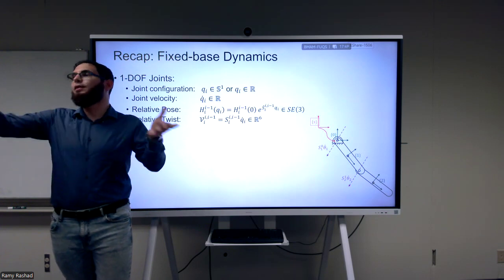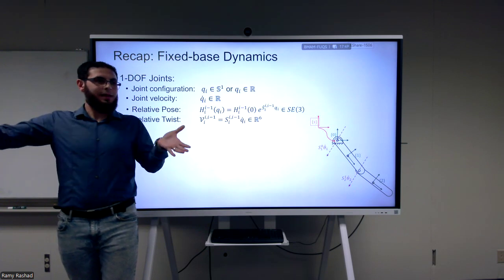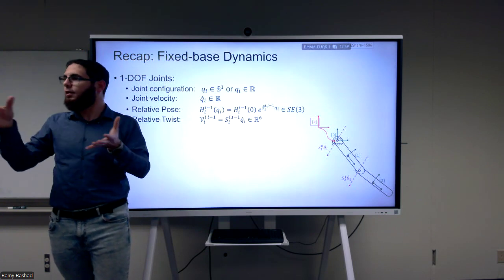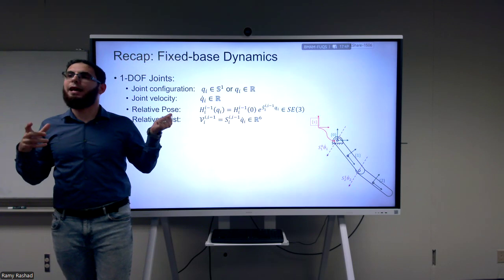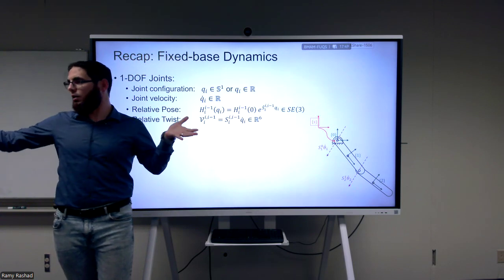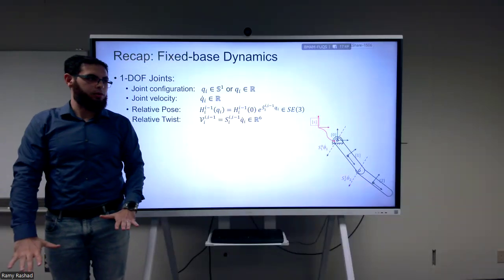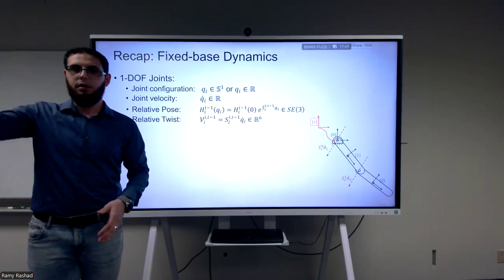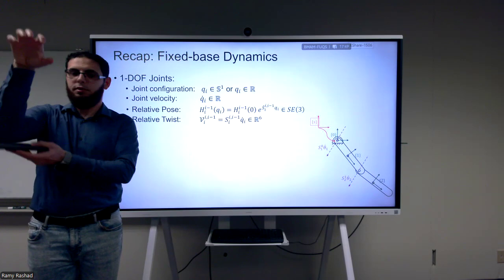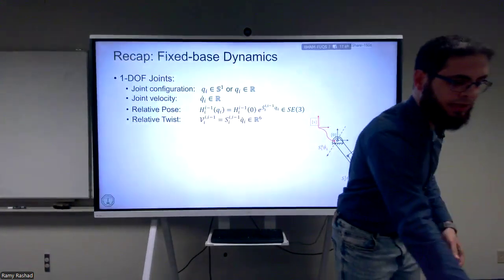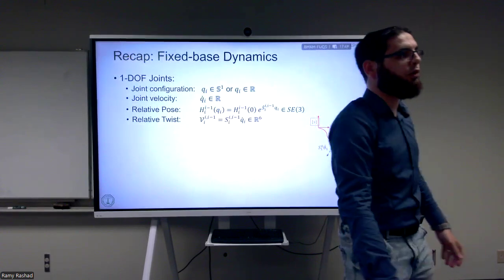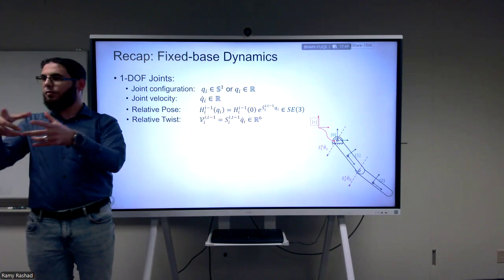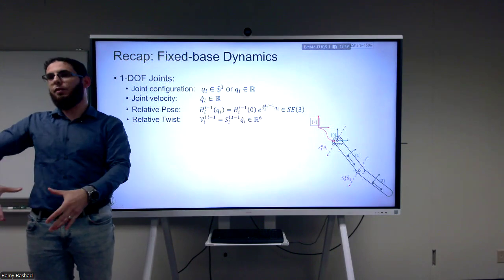Something that's really floating, okay? That's really not moving at all, it's floating in air. It's the same term that we use as floating in English. But floating base manipulators can model a wider class of systems. If you have something that's moving on the ground, okay? Assume something that you have, maybe it has like this thing. Let's say that I put a manipulator on it, and I put it on the table, and I start to move it. Is this a floating base or not? Yes, it is also a floating base, but it's constrained. Exactly. So it's like this base is attached to the stationary frame with a joint, right?